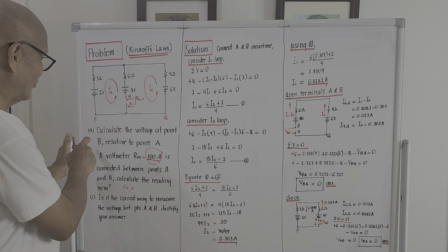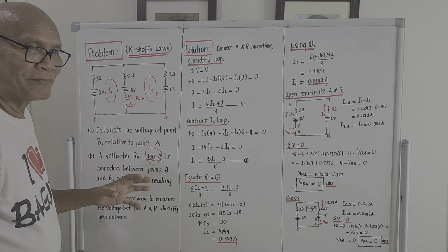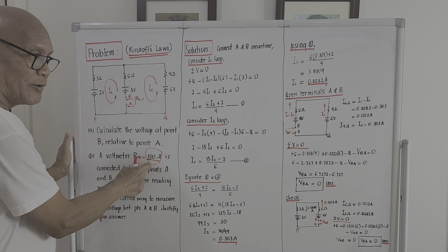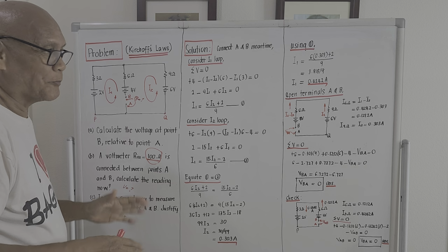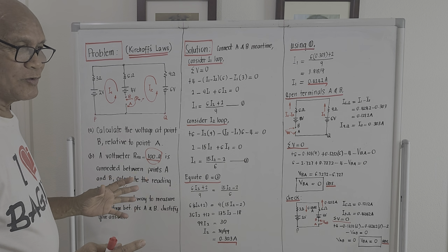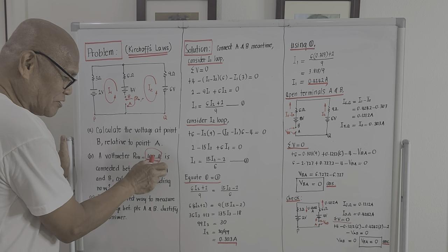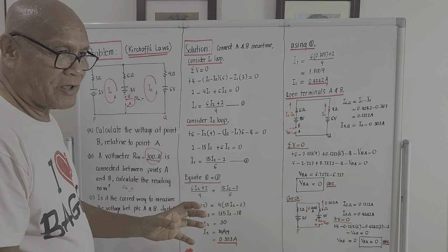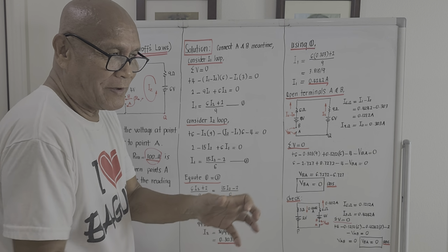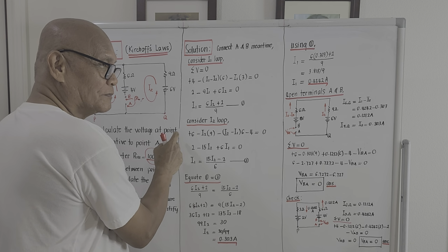Whatever the reading we calculate on A, it will be the same because it has no effect. But since the internal resistance he had given me is too low, it has an effect. Of course, the reading will be different. And I would not like to accept that the internal resistance is just 100 ohms. It should be in the range of 10 million ohms for it to have no effect. And if it had no effect, the reading on B should be the same as in A.